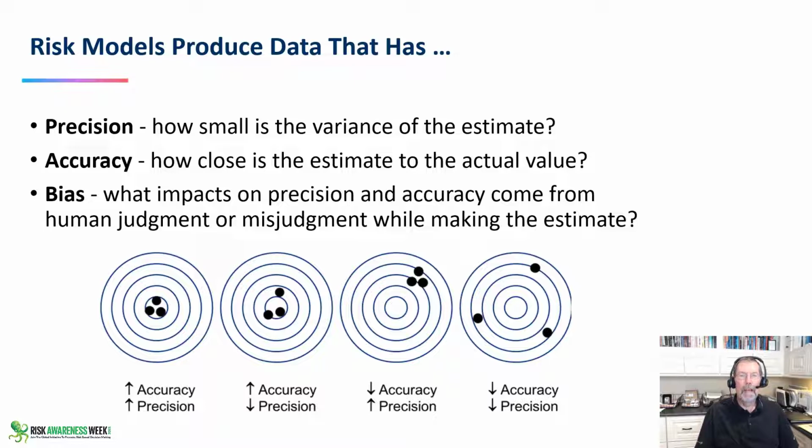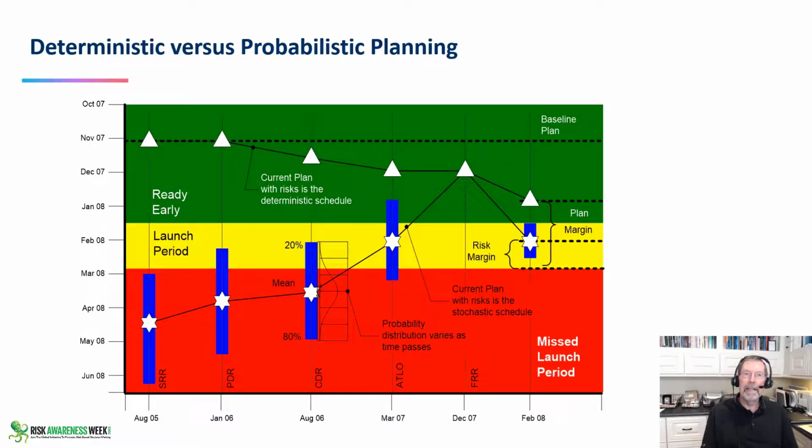This is one of the reasons that professional advice and professional opinions are some of the least reliable and least precise and least accurate opinions about how something's going to either fail or work or not work. We need actual data. And then the next thing with this precision and accuracy and bias is we need to know whether it's a deterministic estimate, that is, I have a number, 27 is how many amps it starts on stall to start the pump motor, or is it a probabilistic number? It's 27 plus or minus 20%, depending upon the temperature and the load and the last time the motor stopped.